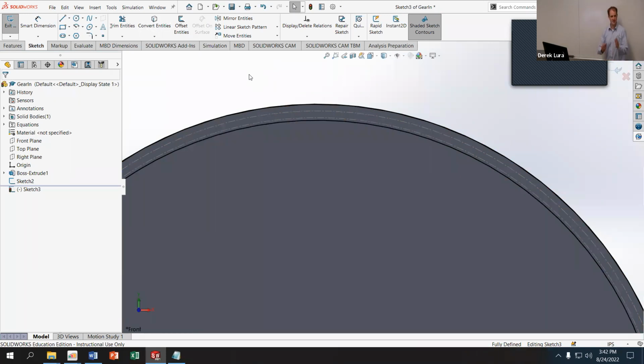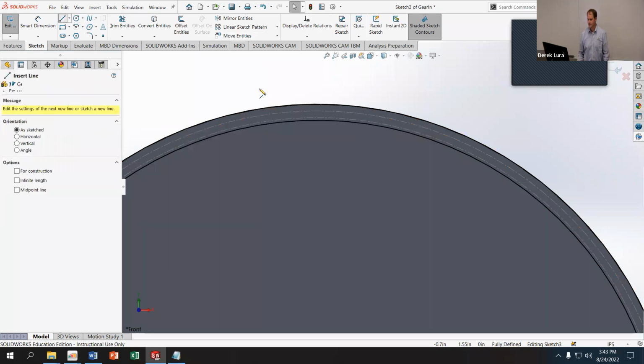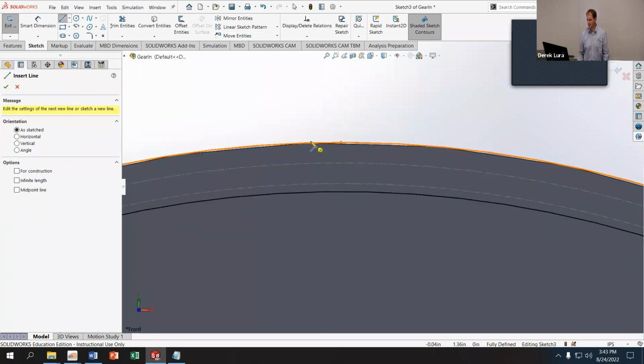And then what I want to do is make two angled lines that go across my part. And I want a point which intersects those angled lines and my effective diameter, because that's where I want to set the pitch of the cutout, or really half of the pitch. I'm going to do this on the top just for convenience.